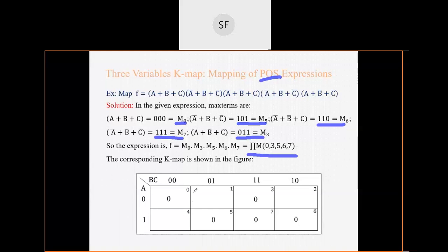Then you have to draw this structure, this K-map for 3 variable. Okay, so initially all cells will be blank. You know the cell suffix. Okay, so these cells are nothing but 0, 1, 3, 2. Again remember that 3 is earlier than 2. Again 4, 5, 7, 6. Also remember this, 7 is earlier than 6. Okay.